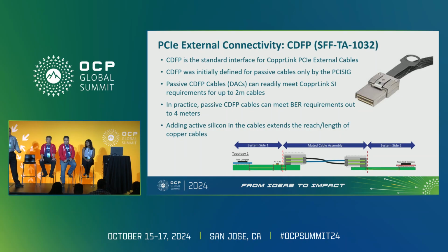So the standard for external PCIe connectivity is the CDFP connector, which is standardized by the SFF-TA-1032. CDFP has been around for quite a long time. It actually was developed over 10 years ago for Ethernet connectivity, and then improved gradually to meet the speeds we have today. When it was originally designed into the CopperLink spec, it was really thought of as a passive-only type solution. TE and some others worked to add power to it in order to enable it to be a truly fully active solution as well.